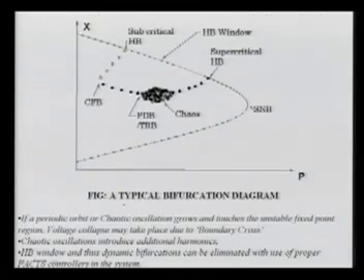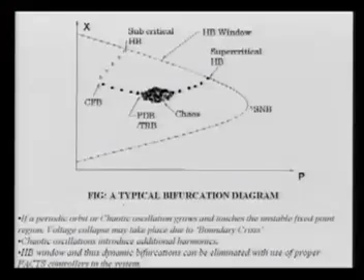Now all these dynamic and static bifurcations, you can see here in one diagram, so this is a typical bifurcation diagram. First I explained the saddle node bifurcation point, which is here, and I am trying to give it to you on this plot. So this is your real power, here it is your voltage, that is the X vector, and this point is your saddle node bifurcation, because here it is stable and this is unstable. So it is the point where stable and unstable meet, and this is the nose point or saddle node bifurcation.